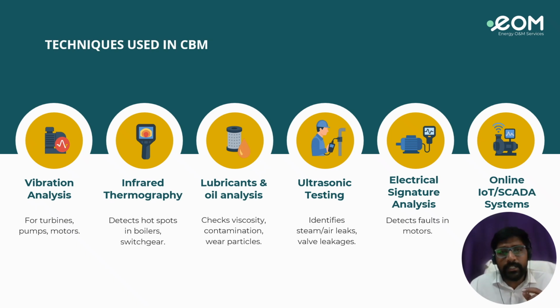The next one is electrical signature analysis, which helps in monitoring the current and voltage waveforms of the motors and generators to detect abnormalities in both the electrical supply and mechanical load. The signal is analyzed in time domain and frequency domain. Any changes in electrical signals indicate mechanical or electrical issues. And the last one is real-time sensors and IoT platforms. It deploys smart sensors connected through IoT for continuous data streaming, and it provides dashboard accessibility to all management levels, enabling data driven decision making as well.